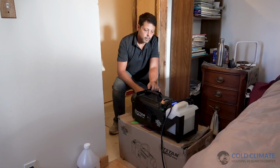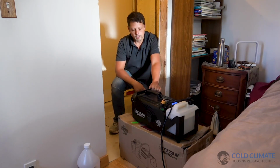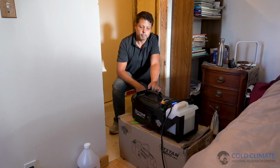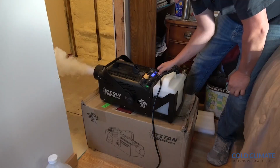We just set up the fogging equipment here. It's a commercial fogging system. Here we're going to be testing and mapping out the air leakage pathways through a building envelope, and you can start to see it's ready to heat up now. We're going to turn this on and fill this space with fog. We've got the blower door system set up and pressurizing the home so that we'll be pushing air through the wall system, and with that all the fog, and we'll be able to map that through at the exterior of the home.